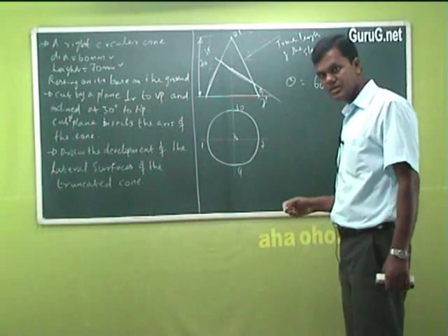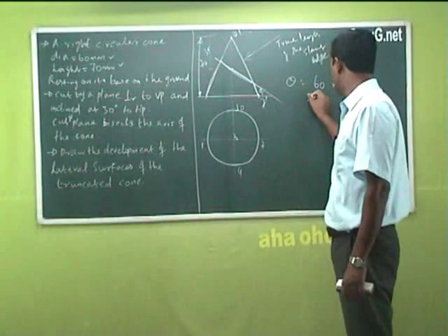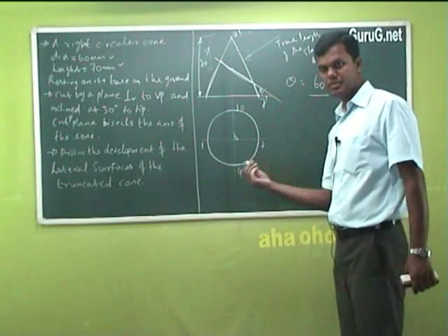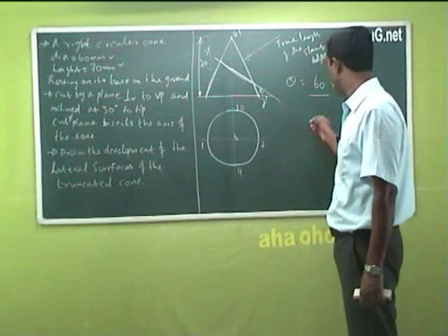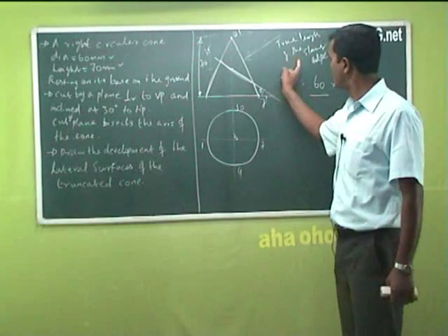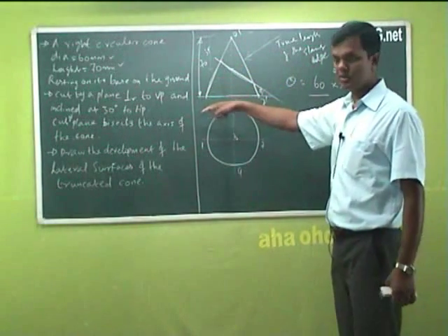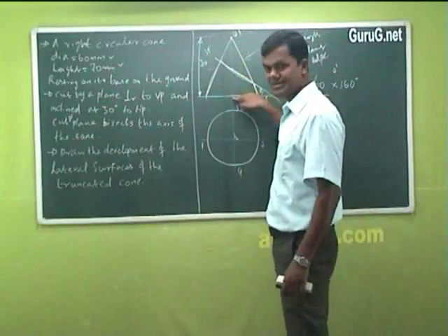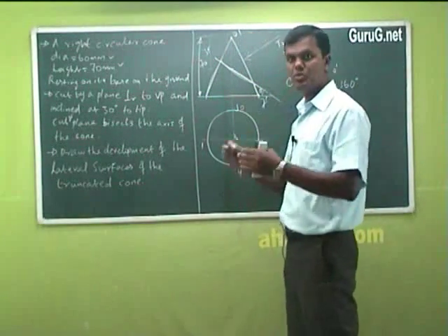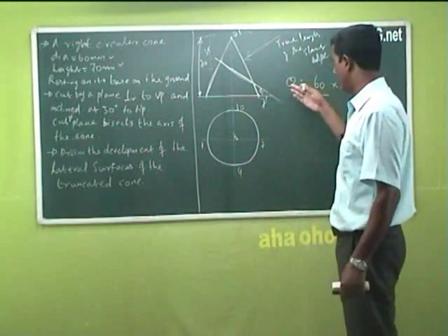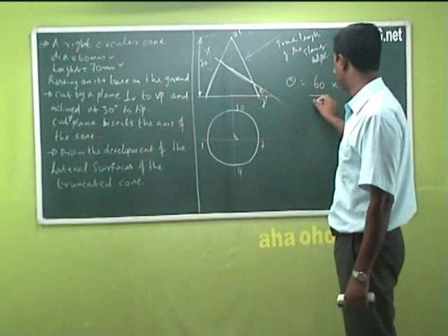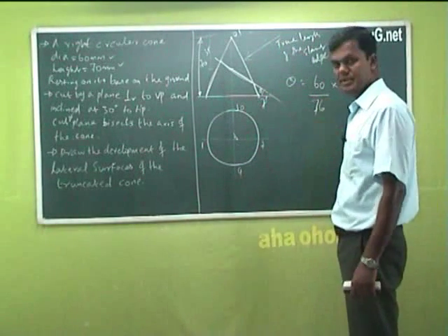That is 360 is the total angle for a cone, because the base is a circle, divided by the true length of the slant edge. Because 70 is given as the axis, this true length will be something more than 70. Actually, in this question it is supposed to come to 76 millimeter.